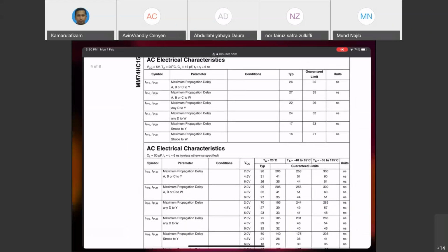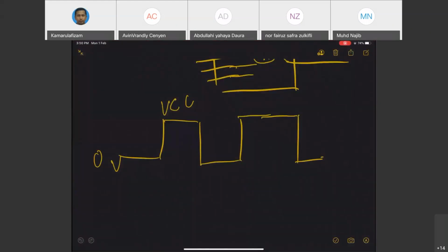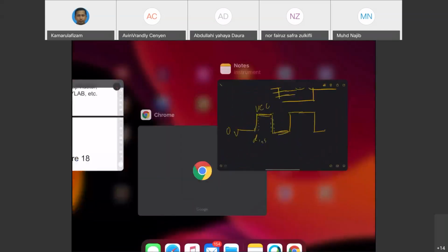You have to know that from here to this point there is some kind of delay, in terms of seconds, and you have to make sure this is right so that the multiplexer has sufficient time to read your logic level, either 0 or 1. So that is how you should work with the multiplexer.